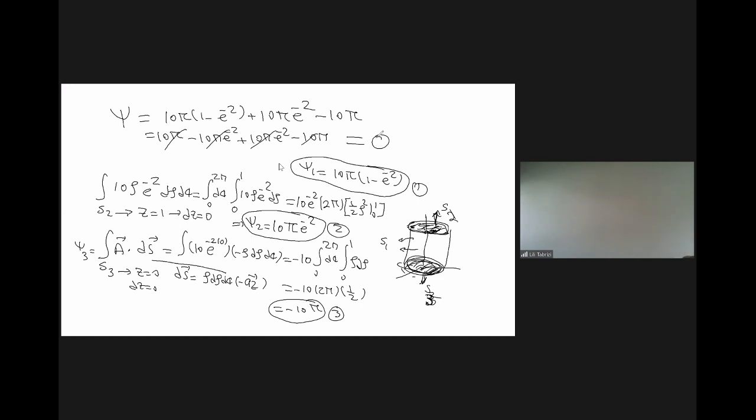You may say, okay, in order to find flux, which is a very important part of electrical engineering, finding electric flux and later magnetic flux, it's too much work. Notice that in this case, I gave you a very simple surface. It's too much work: finding psi 1, psi 2, psi 3, breaking the surface into 3 parts, and performing an integral for each part. Is there any way to avoid that? And the answer is yes, the shortcut is the divergence theorem.